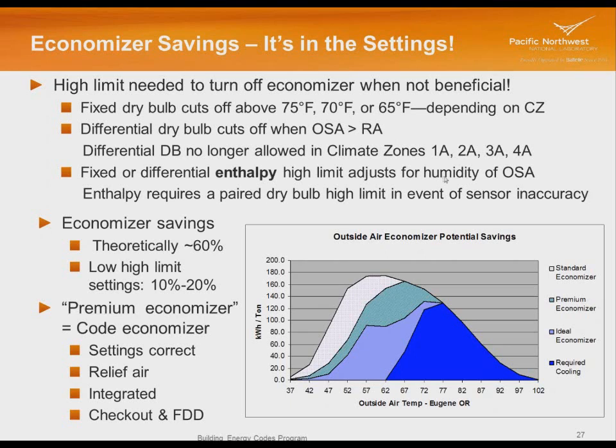And it adjusts for humidity with the idea that if the air is humid, even if it's cool, all that water is going to come out in the cooling coil and increase energy use, so it may actually not be helpful to bring in the outside air.